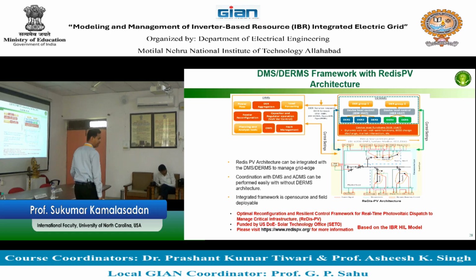So you can now make this management architecture for multiple batteries and multiple PVs. This architecture is also implemented as a tool. This is how the power grid operates. And this power grid management system on a distribution system is called DMS. Have you heard of this term? DMS, distribution management system. The DMS actually does power flow, load forecasting, feeder reconfiguration, capacitor improvement, OMS, outage management system, and fault management. These are the kinds of things which are DMS.